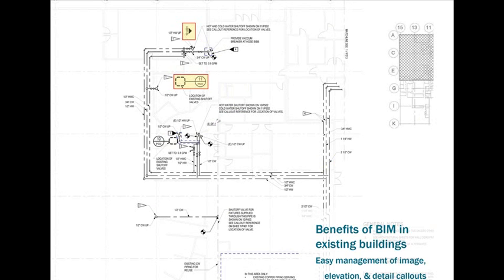Some benefits that we found through using Revit on this project were that we were able to speed up production considerably and increase the amount of clarity in the drawings by including pictures. I didn't include an image of what this is actually pointing out, but in that location it says, location of existing shutoff valves. I found a shutoff valve the contractor needs to know about in order to maintain this phasing plan. So I took a picture of the valve and put it in my project. I put it onto a detail in a separate sheet, and then I put a little detail bubble around it, pointing to that picture. So I can tell a contractor, this is a shutoff valve right there, and this is what it looks like. That's something that would typically take a lot more time in CAD than we would expect to spend in Revit, and that's one thing that's nice.